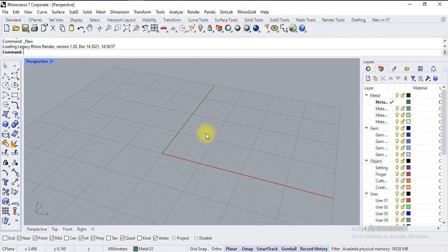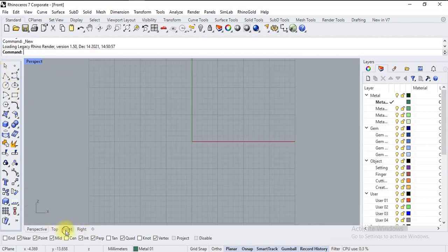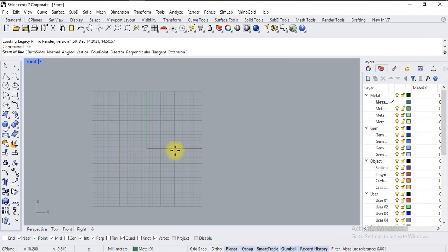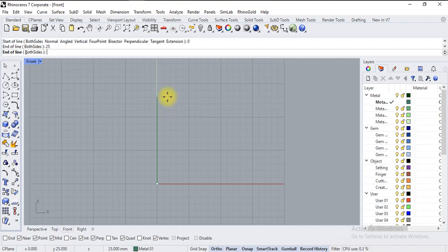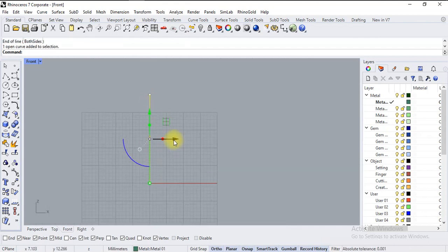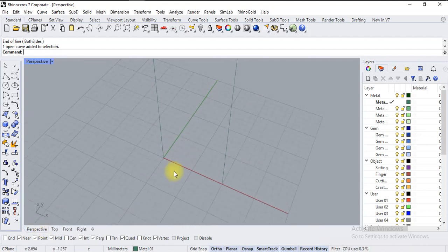Let's make a revolve. Let's first make the revolve line. It should be from 0 and a straight line. Always go dimensionally. So we'll turn on ortho and specify height 25 in this direction. In a similar way, I want an offset. Keep pressing the Alt key, click on this arrow and specify distance 10. So this is 10 mm away from this line.